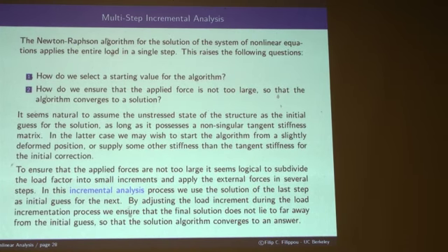all right. No matter which method you use, the way I presented the algorithms before, you will see them posted. I didn't discuss them with you because I'm sure you probably know what a typical Newton-Raphson algorithm looks like. The issue is that you are not going to do a single step. You're concerned, first, with picking the starting value, the initial guess, and secondly, how big of a load can you apply before starting the process.